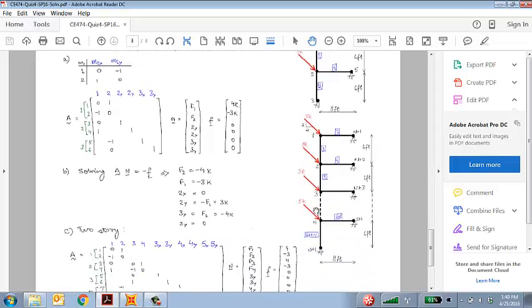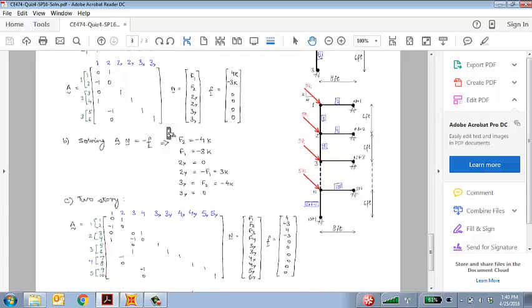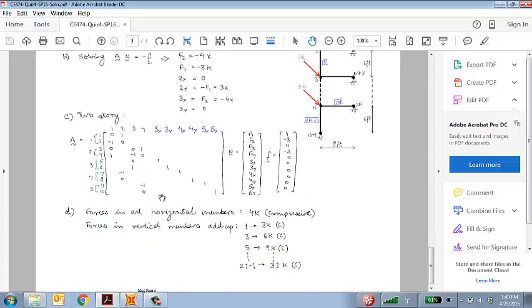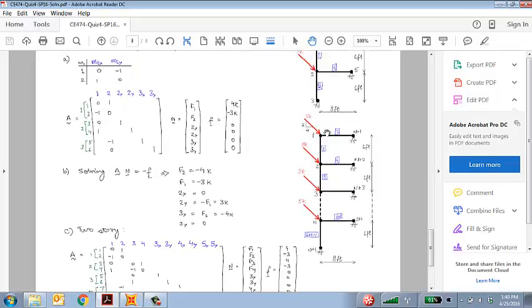And the 2-story and the n-story problems were really just extensions of the same format. So if you look at these coefficients, they just keep repeating over and over for 2-story and n-story problems. And actually, even just by looking at this picture, you should be able to see that the 4 kilonewton force would go into the horizontal bar for all of these elements, and the 3 kilonewton force would go into the vertical element and keep on getting added together to reach the final compression force at the bottom.